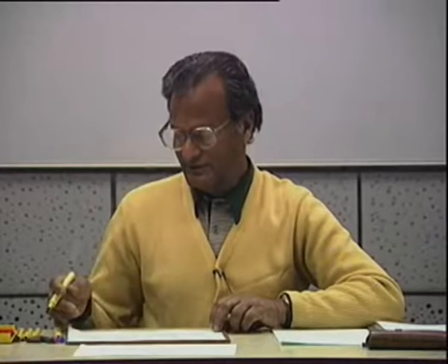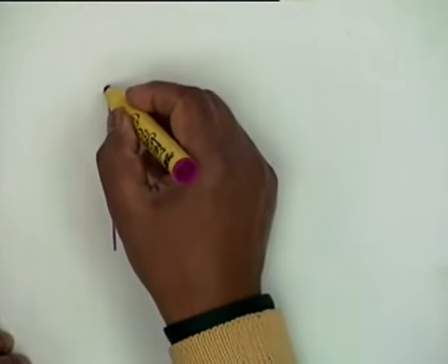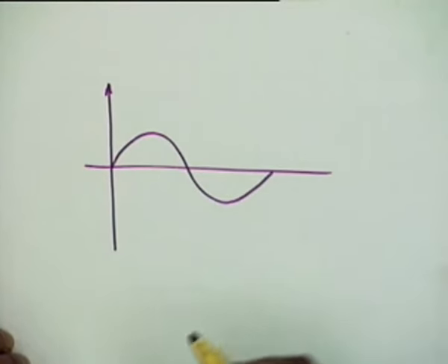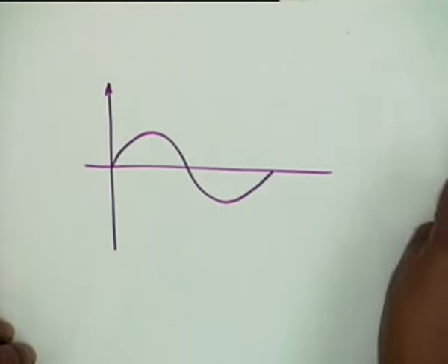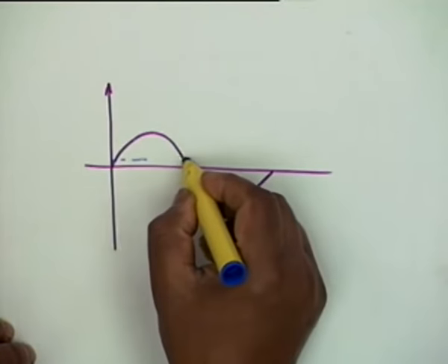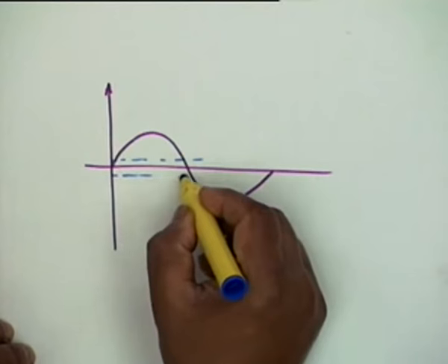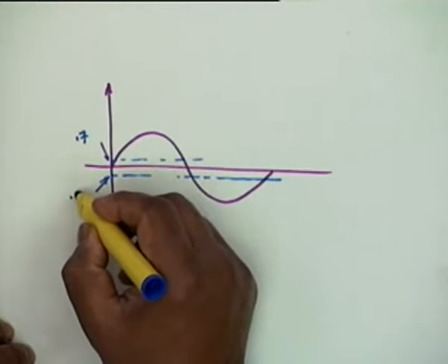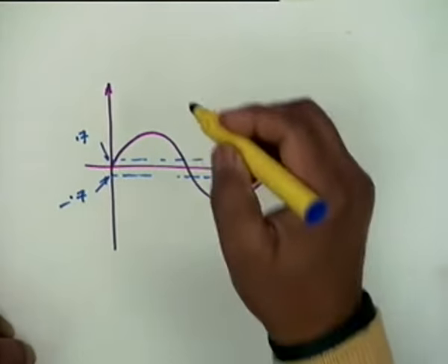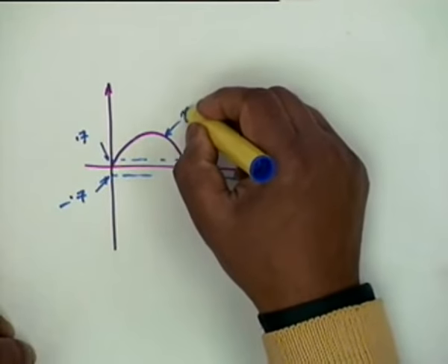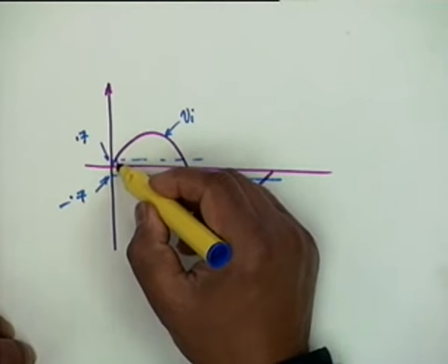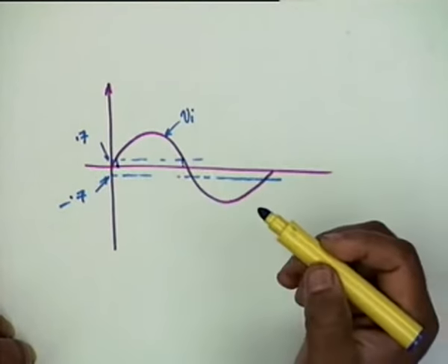And obviously what we will get if we have a sinusoidal input like this, and if these lines are 0.7 and minus 0.7, we take VBE on as 0.7, and this is VI, then V0 would start here and end here during the positive cycle.